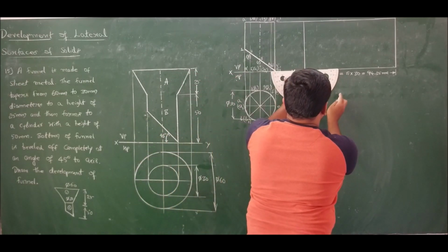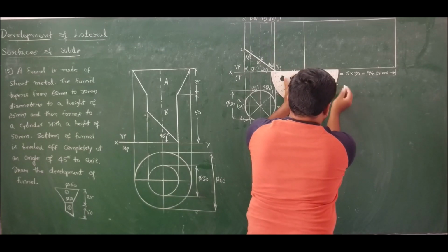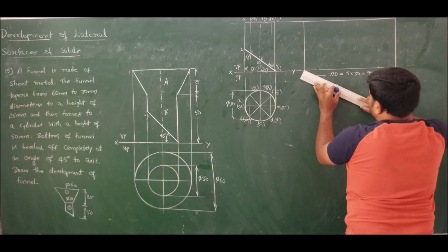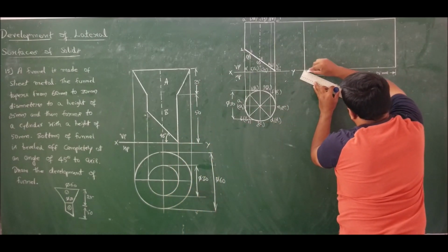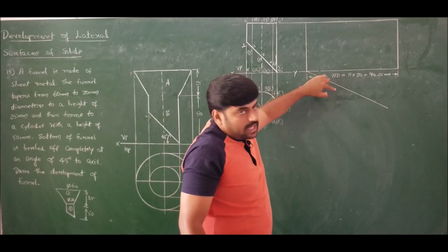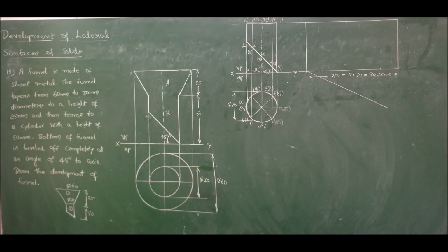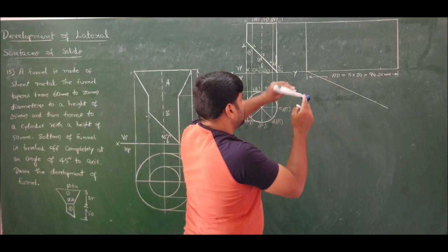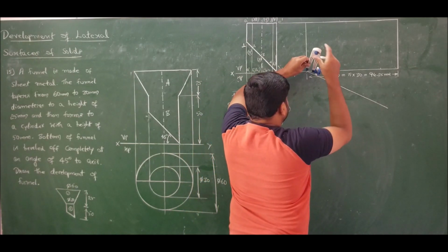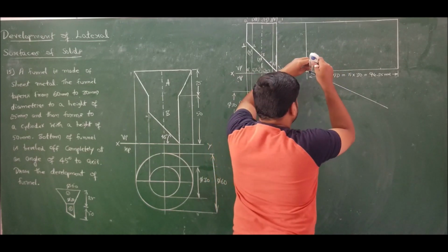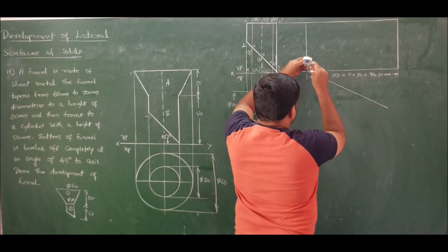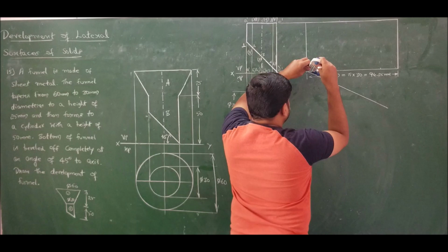First you draw a line at an arbitrary angle, and divide it into 8 equal halves of unknown dimension. So this line length is arbitrary, and the angle is also arbitrary. Now take an arbitrary measurement arc. From the beginning point, you cut arcs at equal intervals. I want 8 divisions. This arc dimension is also unknown. So unknown angle, unknown length, unknown arc dimension. You cut 8 equal arcs on this line.